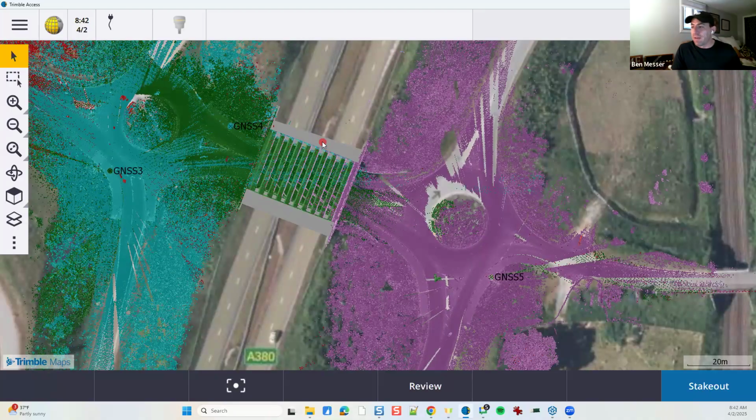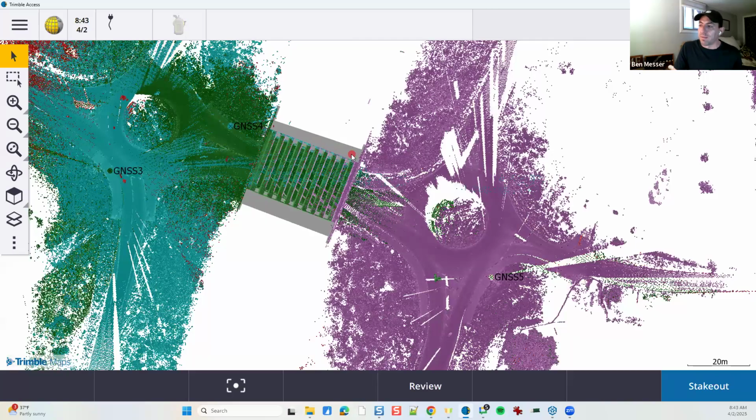If there are 5 other guys working on the same project, same location, they all link it the same way, and they're going to see the same IFC file. It's not imported into my Access project or my job file. So again, if it's a CSV file, we're all working from the same CSV control point file. There's no confusion about who has the most updated.